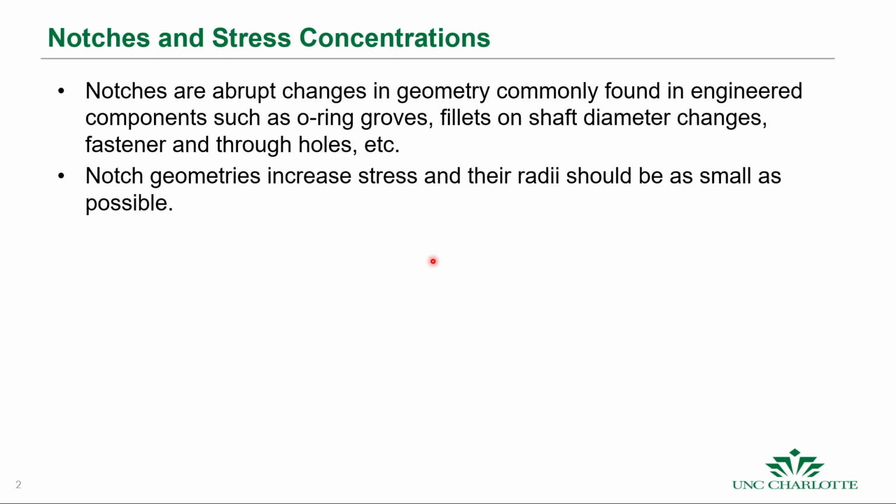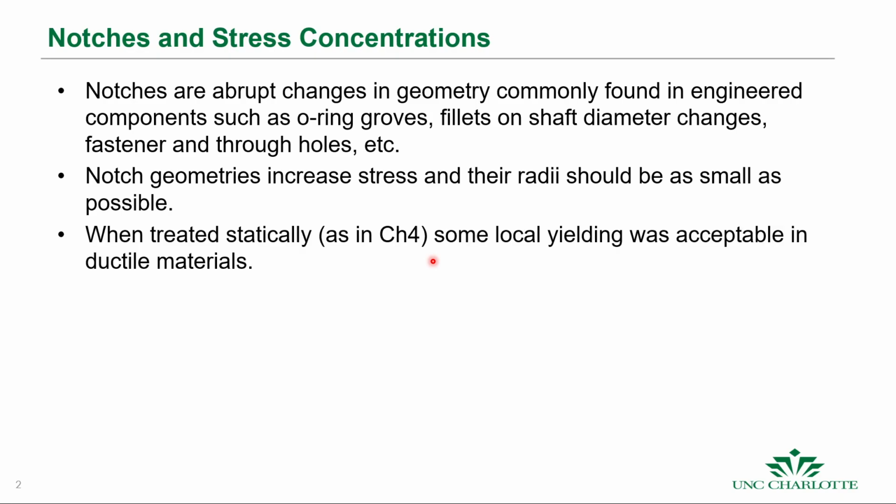Every time we have these changes in geometries, you should always look at them and just see them as stress concentrations in places where your component will likely fail. And what we try to do is keep the geometry such that we reduce these stress concentration factors. Okay.